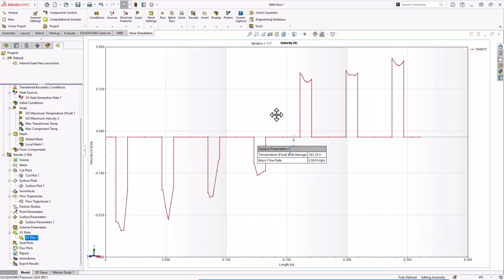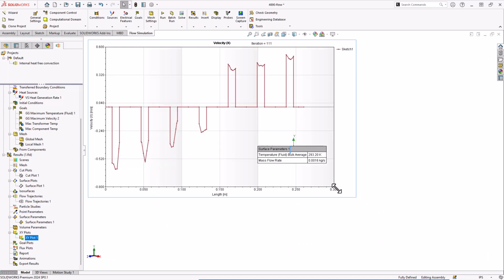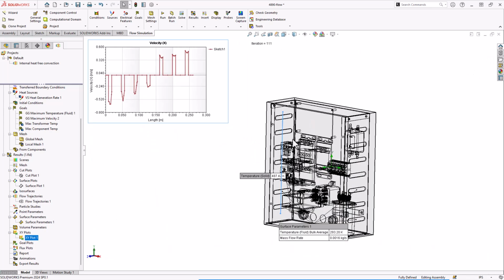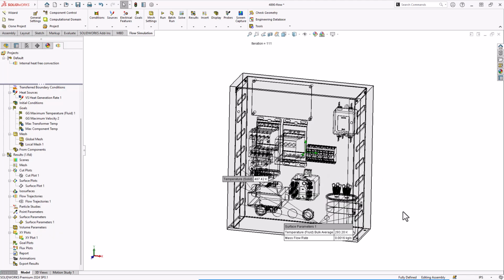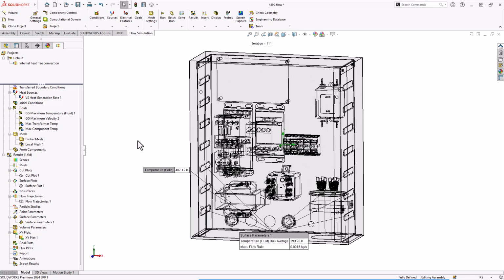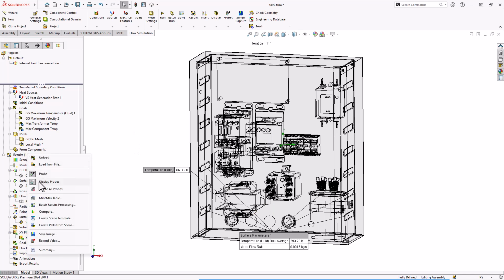is I can see which ones are going in and which ones are coming out, right? I also see fully developed flow. The fully developed flow is the velocity of the air across that, and that fully developed flow is different for each one because it's either coming in or it's going out. So kind of interesting stuff. Just a lot of really cool stuff that, in my opinion, helps you to gain insight into these types of applications. So you can look at these in the future and you can kind of tell what's going to happen based on what's going on.